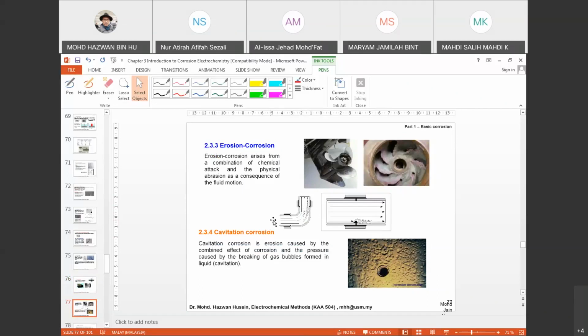So when you have any fluid movement, like water, when it goes to this 90-degree angle, what happens is that this will create a so-called cyclone, and you have more erosion of water here. So when you have more erosion and formation of cyclones over here, then corrosion can easily happen, and this actually can create erosion corrosion.